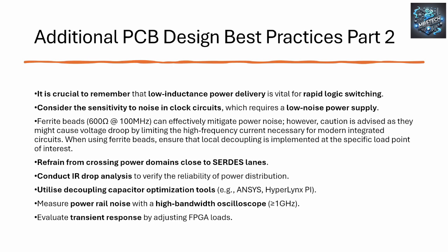Typically when you're doing an FPGA design, you only use about 50% of it. Well, what happens in years to come when the customer says, I want this extra function, and then you try and put that in, the system starts to fall over. Well, you need to fill the FPGA up and run it not at the frequency that you're currently running at, but at a higher frequency, and make sure that you are still having a performance that's acceptable in your system, that the FPGA is not falling over, that the noise floor is acceptable, that there's no voltage dropping, there's no excessive ripple.